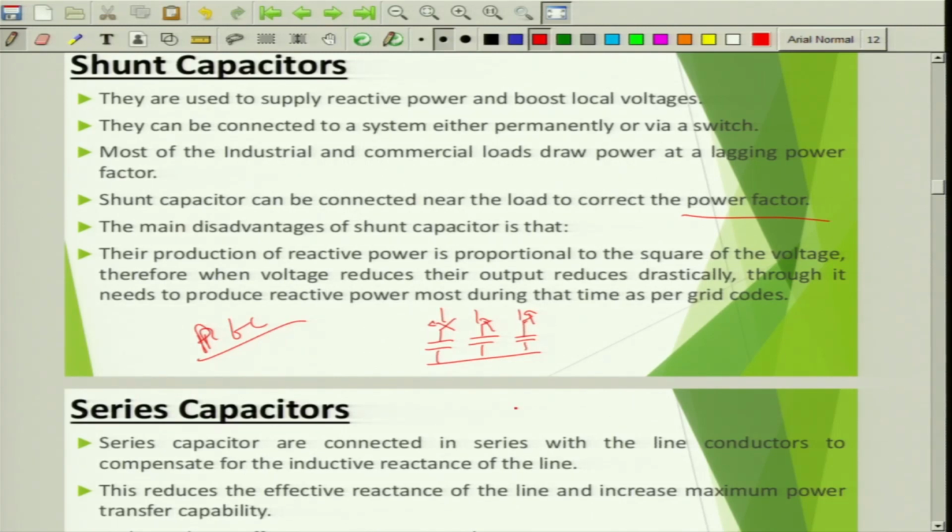You might have heard this, power factor correction devices. They are nothing but capacitors themselves, either connected in delta or star fashion. Because there is a penalty from the Indian government if you do not operate the power factor at least at 0.8 lagging, right? So, you have to pay the penalty. So, what they do is they put these capacitors so that they would manage the minimum requirement of 0.8 power factor.